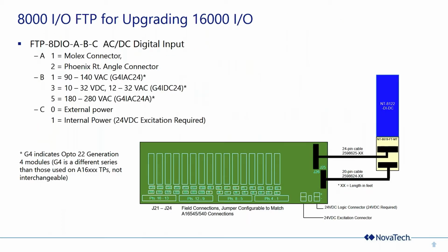Kind of a schematic. Again, as I mentioned, there are a lot of hidden slides, so there are slides for every type of termination panel and I/O in this presentation to provide you all the information that you need to help configuration. It's a reference document, but I'm only going to show this one, and it basically shows a termination panel with the wiring to mass terminations on an 8,000 I/O module. So again, very hard to screw this up. Your point-to-points are not really going to be needed. Just need to make sure that you can talk to the module and it talks to one point out there and it's going to talk to all the rest.